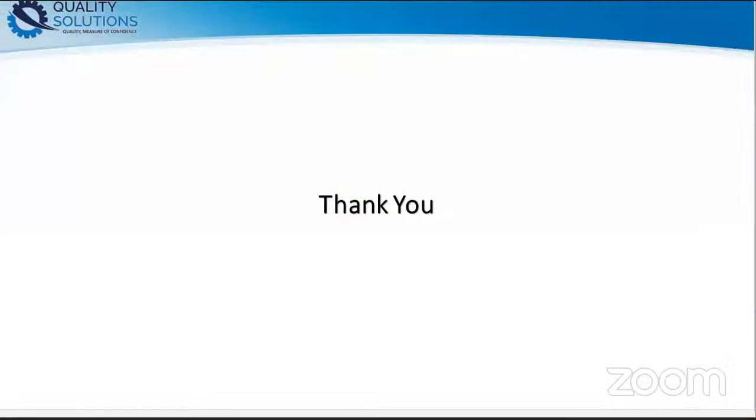So guys, thank you so much for your time. I hope you guys have learned a lot about reverse engineering and how to get the data with the help of a 3D scanner, convert the point cloud data into mesh data, how to modify the mesh data based on the requirements, and then use the auto surfacing command to get the solid body, and then also apply some features on the solid bodies.